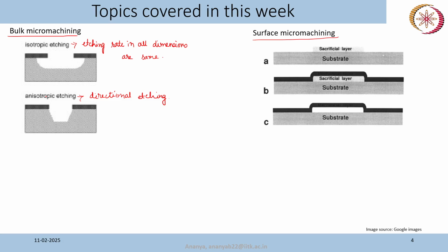Okay. Now usually chemical etching is faster. The etching rate is faster. You will be able to etch a significant portion in less time compared to dry etching techniques. Also, dry etching techniques are usually expensive because they need different types of instrumentation, which are costly, whereas chemical etching can be a little bit toxic and you have to handle the chemicals carefully, but usually you don't need a very sophisticated instrument or environment for this kind of etching. Okay. But the disadvantage is that these are isotropic.